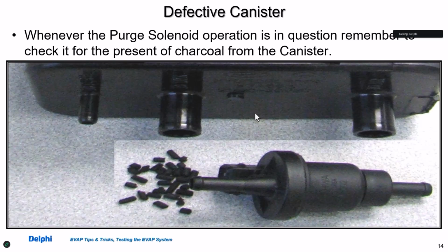They're spring loaded. They adjust for different size engines and different size tanks. So there's some airspace in there, but they're all spring loaded so that they hold the tension on the charcoal canister, granulated charcoal, where they're doing this. So good visual inspection.